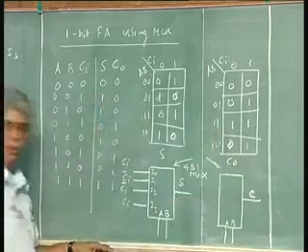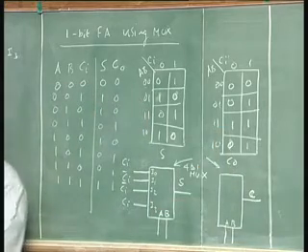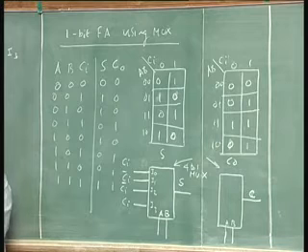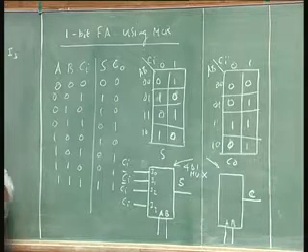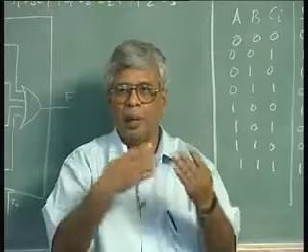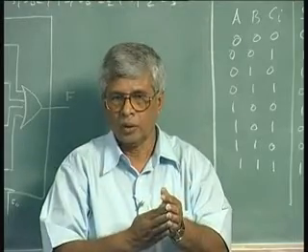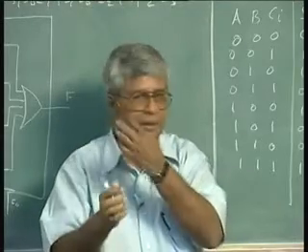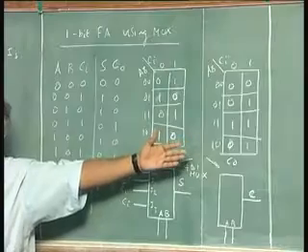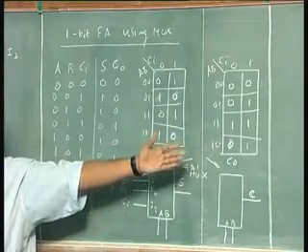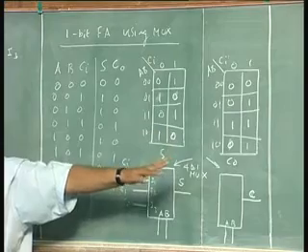From this map I will do this. So I am now mapping onto this given hardware, namely the 4-to-1 multiplexer. It is hardware mapping, not mapping like drawing. The hardware mapping, on a given 4-to-1 mux, the given Karnaugh map to get the function implemented.